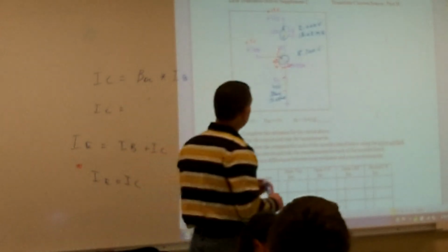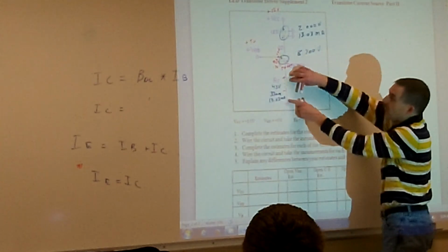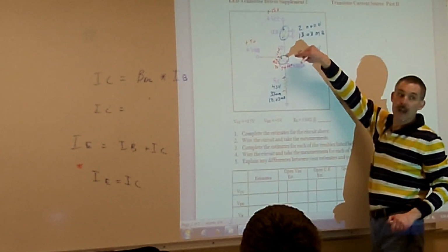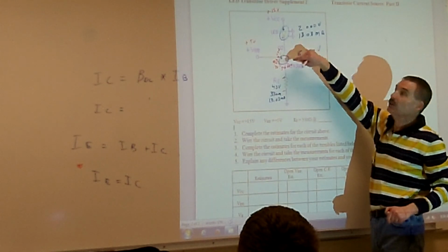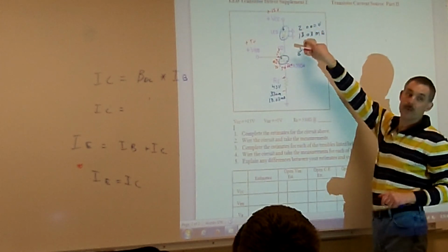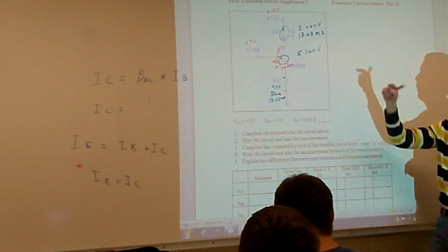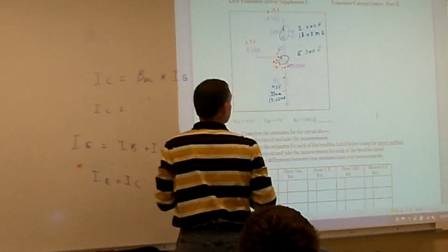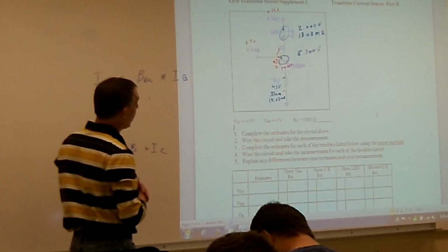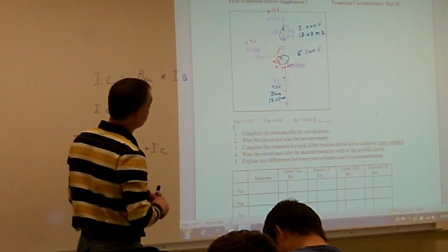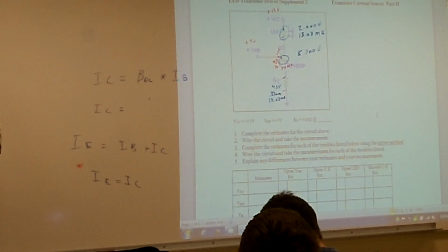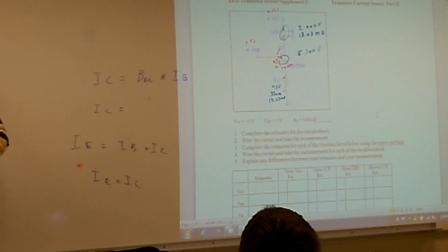And then CDE then, since RE's already determined what the current is going through there, my transistor is automatically going to adjust itself to make sure that it maintains 13.03 milliamps going through my collector. Okay? So that resistance, this time it's kind of more of a variable resistance. This time now what this circuit looks like, the other one actually looks like a closed switch.